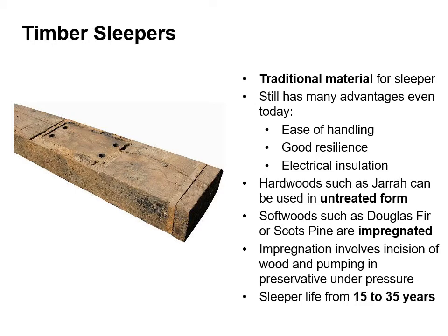Timber is a traditional material for sleepers. It still has many advantages, even today, including ease of handling, good resilience, and good electrical insulation. Hardwoods such as Jarrah can be used in untreated form. Softwoods such as Douglas fir or Scots pine are impregnated. Impregnation involves incision of wood and pumping in preservative under pressure. A timber sleeper can last from anything between 15 and 35 years.